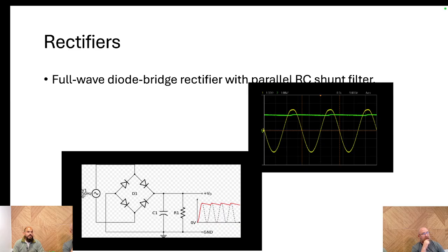So that's at a really high resolution there. Typically you wouldn't see that, because it's doing that 60 times a second. Exactly. It's going so fast you're not seeing it. And actually, each hump there is a 120th of a second, because it's flipping the negative one up positive. So there are two humps for every cycle of AC.